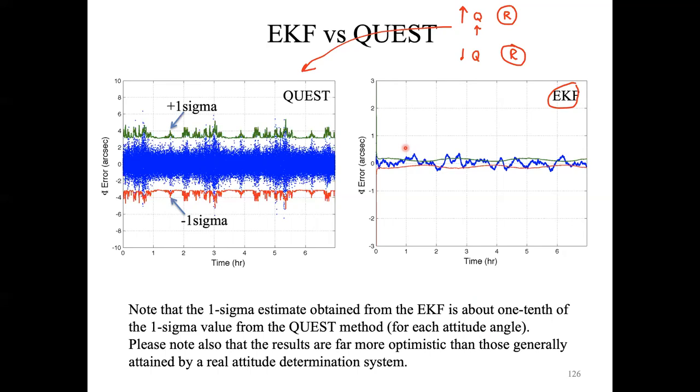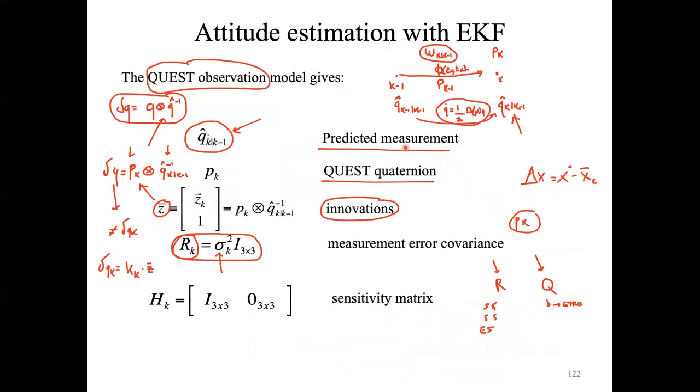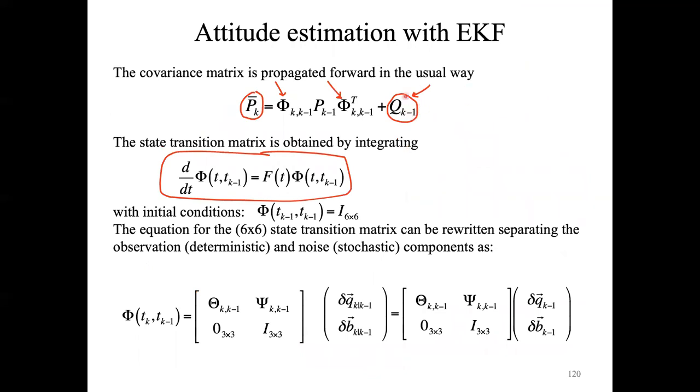So you restart from a certain epoch at which you re-update Q, and so over time Q will vary with the propagation matrix gamma that we have seen yesterday. So your point is correct. In principle, you can use your observation to update a theoretical, statistical model of the error given by the gyroscopes. So basically, you reinitialize the filter in order to have a sort of retuning of the filter, because that information is indeed useful to know how the gyroscope is behaving in that period of time.